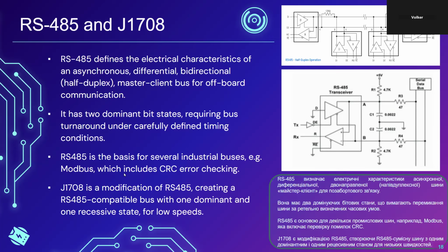In modern microcontrollers like the STM32 series, you can invert the output signal from the transmit line just by clicking a checkbox. It can be inverted in software. So you don't need this inverter in hardware when using those microcontrollers.